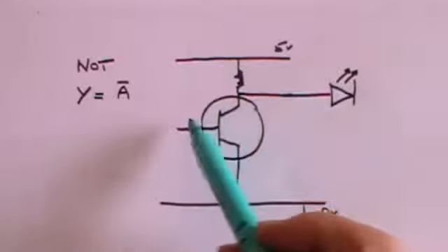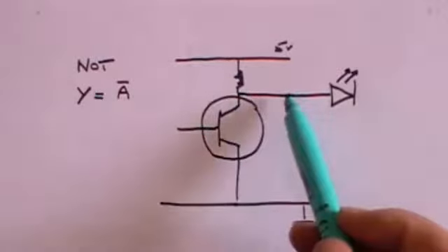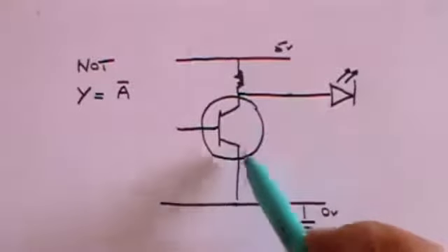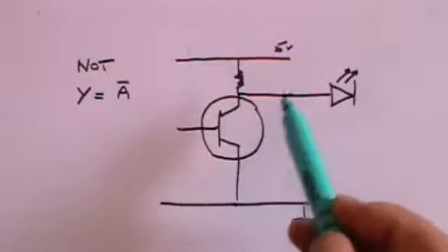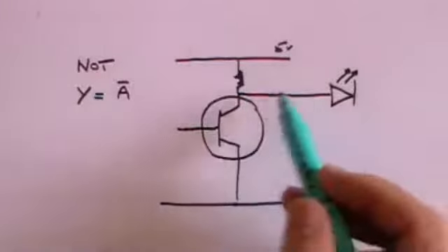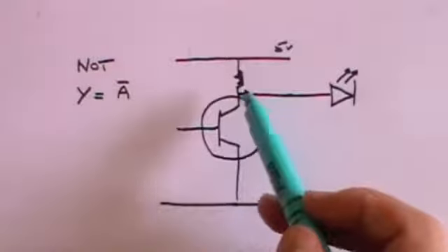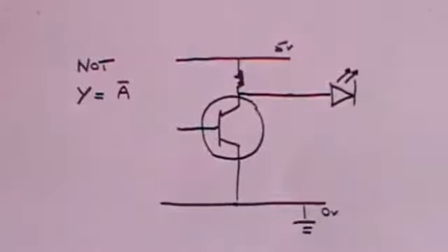And so you've now got a positive voltage on the base, the input, but now no voltage on the output because a current is flowing through here, and so essentially this and this are at the same potential. And that potential is 0. And so this potential is 0, and the whole 5 volts is dropped across the resistance here. So this is simply an inverter.